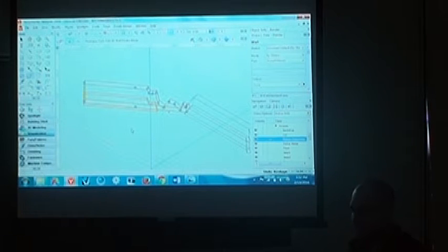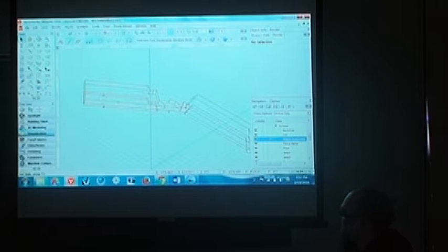So you can very quickly create interesting shapes from your walls. And that's how I did this. I just kept adding vertices and playing around with it until I got the T-Rex having broken through the wall. So that's the 3D Reshape tool.